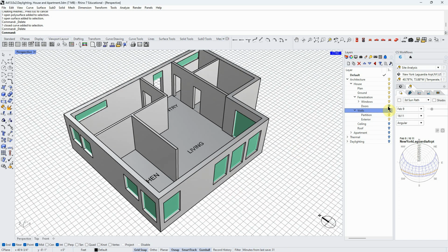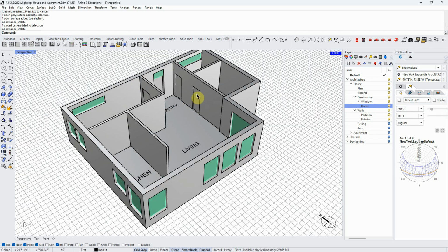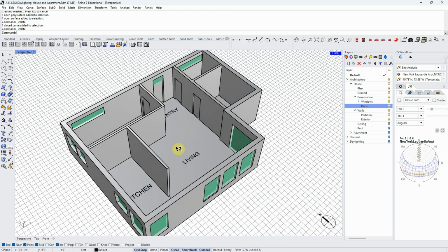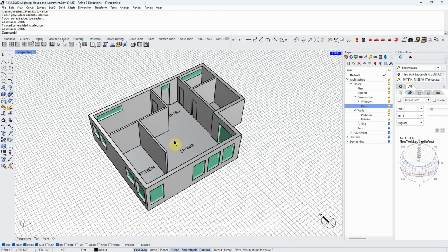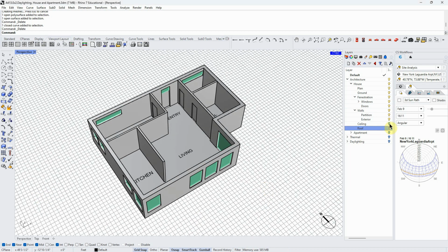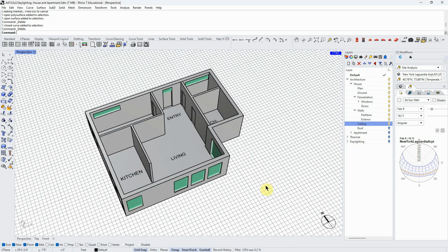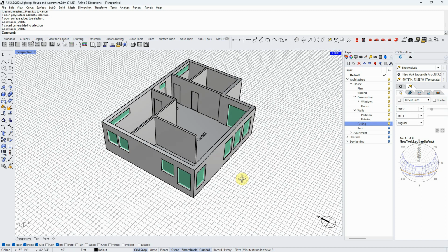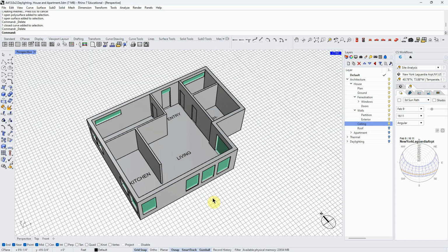So now I did the same thing with the doors, set them in. If it's an opaque surface in the models we're doing, it's not going to be as important. So whether or not that would be set in would be irrelevant here, or pretty much irrelevant. Another thing I mentioned in the assignment is that you want your ceiling to be transparent. That's something you can do next week when you're adjusting your model, but just realize that if you think about it, we need to have a surface here, but we want to be able to see through it sometimes, like when we're doing a daylighting analysis. So that's why that's there, for daylighting.